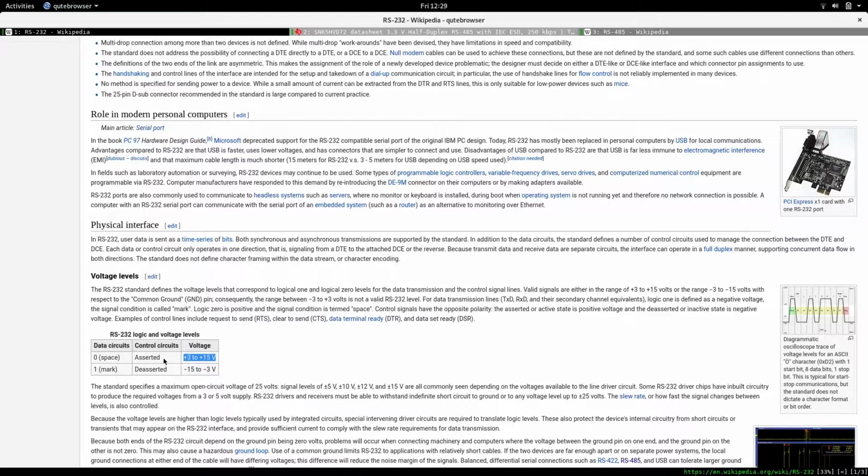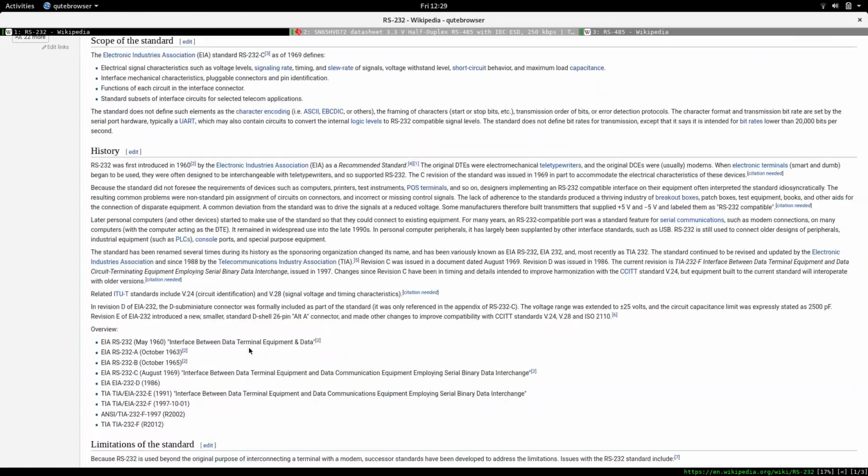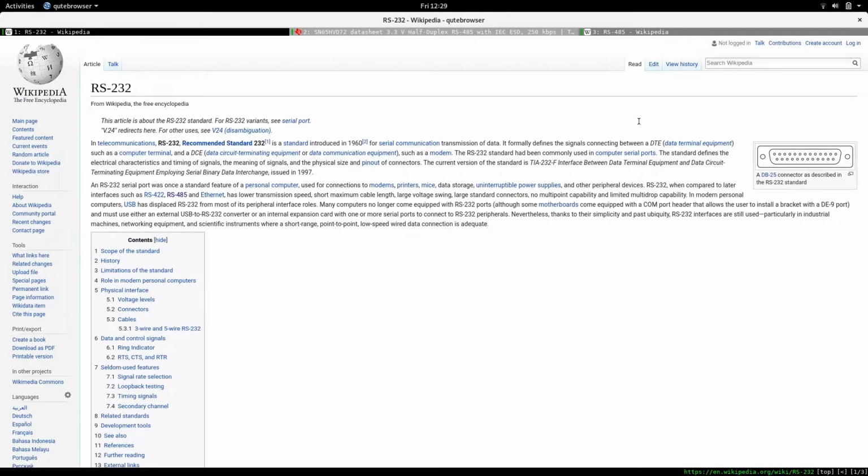That's why we had a transceiver the last time, to bump up that voltage, because some devices expect that high voltage. So when there's a 0, a space, communications sometimes talks about marking and space. If there's a space, the 0 logic, it's a high voltage. It's kind of the reverse of what you'd expect. So that was our 232.